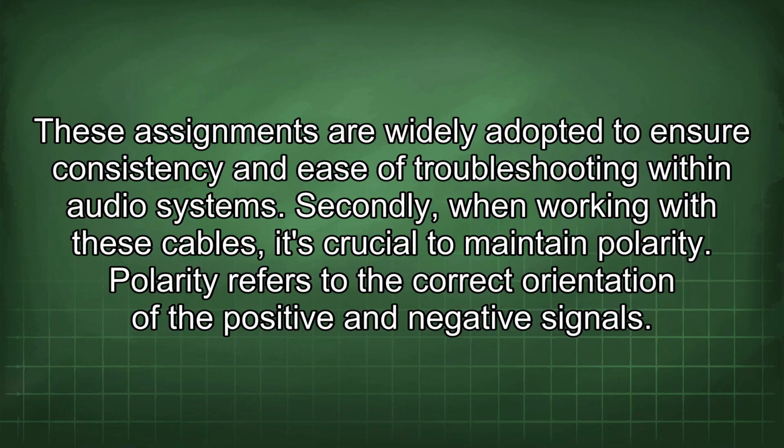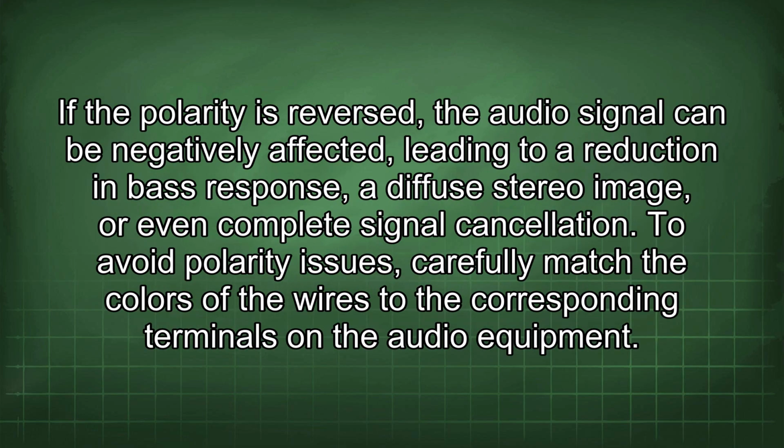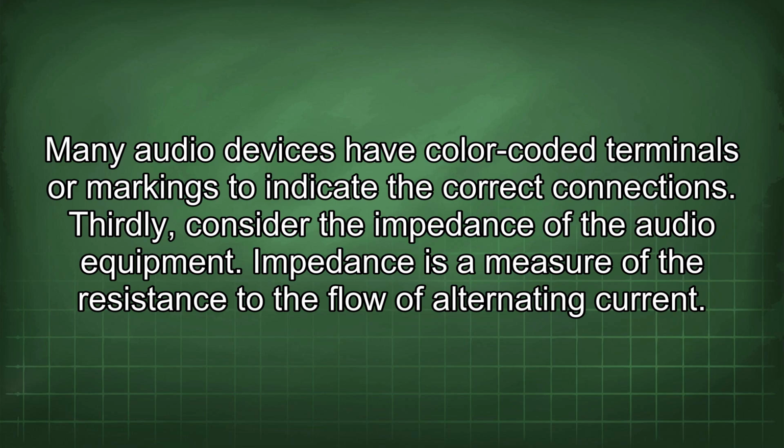Secondly, when working with these cables, it's crucial to maintain polarity. Polarity refers to the correct orientation of the positive and negative signals. If the polarity is reversed, the audio signal can be negatively affected, leading to reduction in bass response, a diffuse stereo image, or even complete signal cancellation. To avoid polarity issues, carefully match the colors of the wires to the corresponding terminals on the audio equipment. Many audio devices have color-coded terminals or markings to indicate the correct connections.